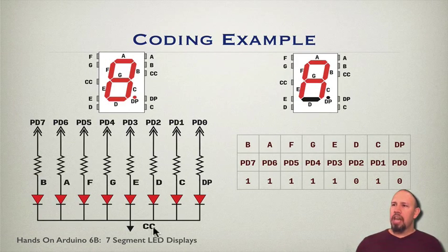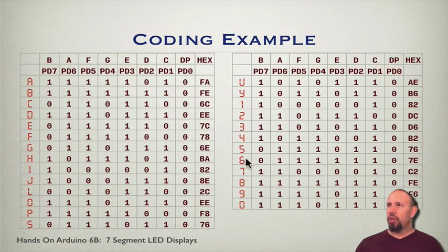This is a common cathode display. Again we have this somewhat random order, and in this case the digital pins do not have to be asserted low, but here we have them connected in, and here is how we would do the display of the letter A. Notice in this case it's just the exact opposite. It's asserted high instead of asserted low.